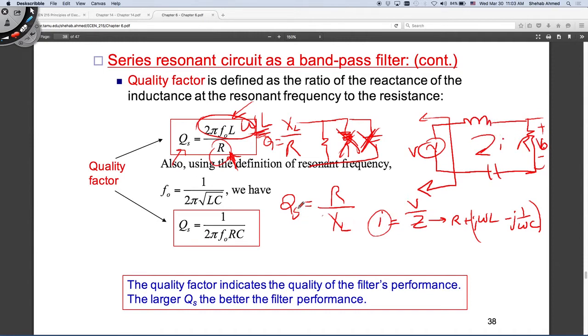Here, what does this tell us? It tells us that if I'm in parallel resonance, I would like to maximize this. Before, I had current going here and here, right? Before, I had current going into the L and into the C. If I make the L and C impedances the same, the current will all go through this resistance here. So it makes a lot of sense that I try to maximize R versus XL, because XL will disappear. These will disappear at resonance, right?